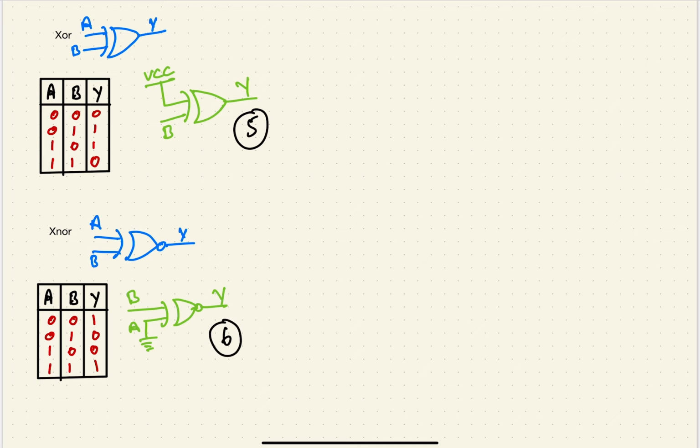So now it is time to see how an inverter is converted to the clock generation circuit. If you talk about the inverter, it looks like this, and the inverter is converted into a clock by giving some internal delay, TPD, propagation delay. And we also have to make one more connection, that is a feedback connection.